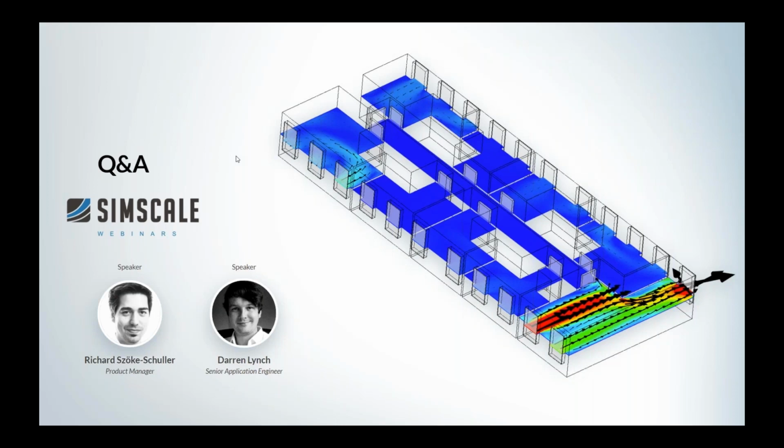When we feed this into the indoors simulation, we're going to use that information to help identify where flows are moving through stairwells, where flows are moving through elevator shafts to counter this stack effect. So it's really the extra information that we can use towards mitigating these scenarios that can really help us here.